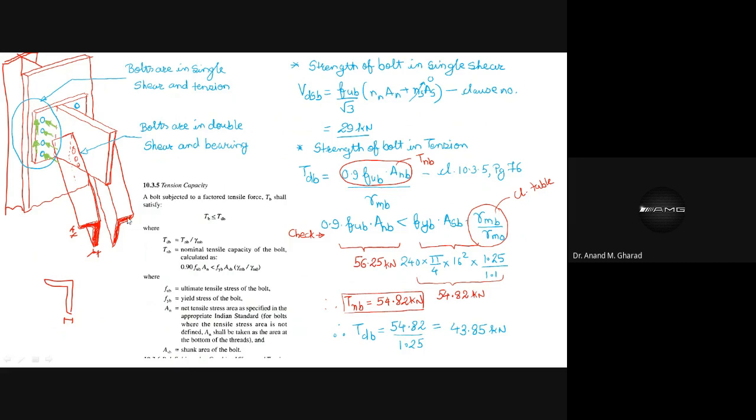Whether the bolts will experience single shear or double shear in this complete portion. Double shear. Why? Because there are three plates. Two are what plates? One is this angle section, the L angle section, and the second is the web portion of the T bracket.